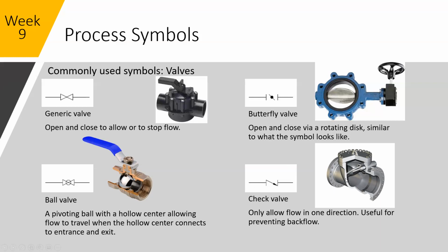I've also seen this type of slanted disc check valve connected to a pump. The pump would push against it, and as the pump built up enough head pressure to start moving enough water, the check valve would slowly open. So sometimes these check valves act as double duty to allow your other mechanical equipment to run more efficiently.